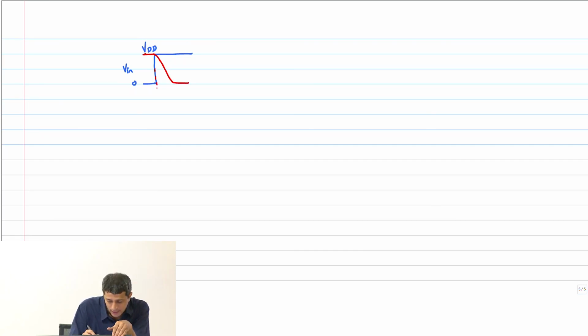So this delay we said was 0.693 R equivalent into C. Now what am I saying? I am saying the input itself is rising slowly. That means the output is actually going to take that much longer.